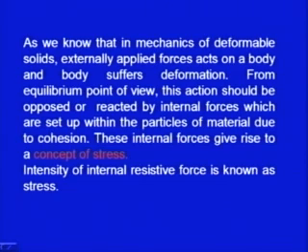One is the elastic deformation, one is the plastic deformation. Since the body is deformable, we can distinguish these two terms as elastic and plastic deformations. And since we know that under these variety of forces the body is under equilibrium, from the equilibrium point of view, this action should be opposed or reacted by the internal body forces which are set up within the particles of material due to cohesion.